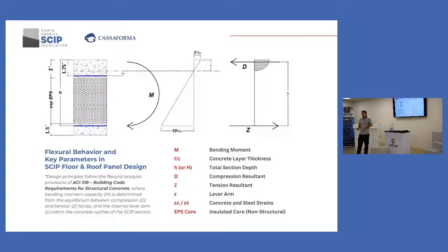Another thing is that when you place more concrete there, you get more load. So the moment goes against you in that case. But below, the difference between the top and the bottom is that the resultant of the tension is always in the same place. Where? On the wire. There's no other way that it can move. So even if I make the layer thicker, the resultant will be the same, and the lever arm will be in the same place. So it doesn't help me that much.